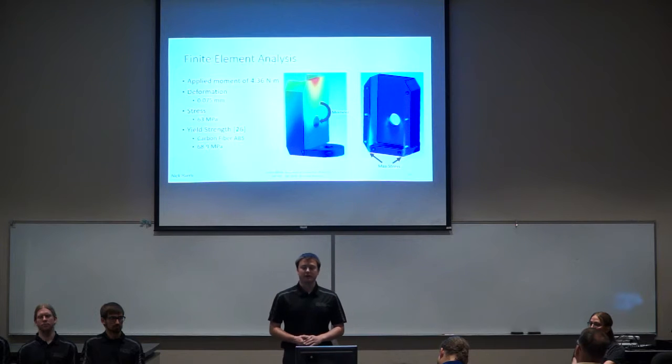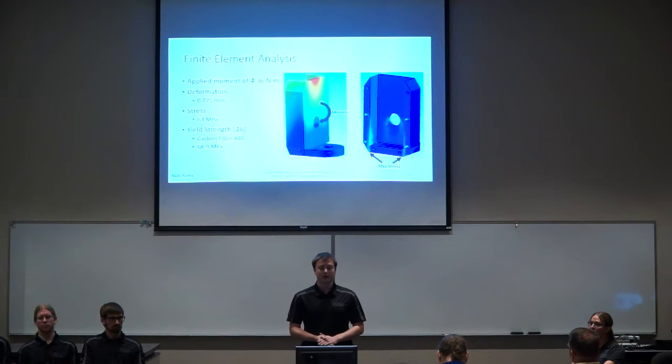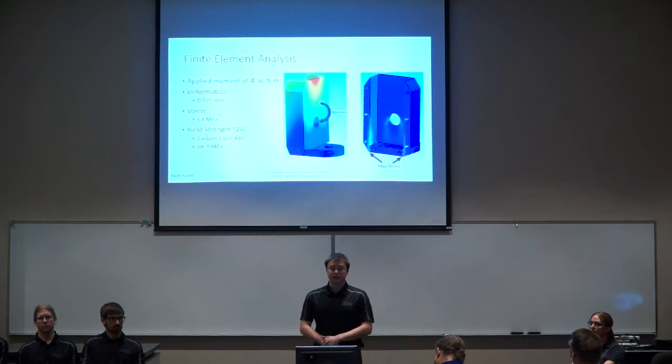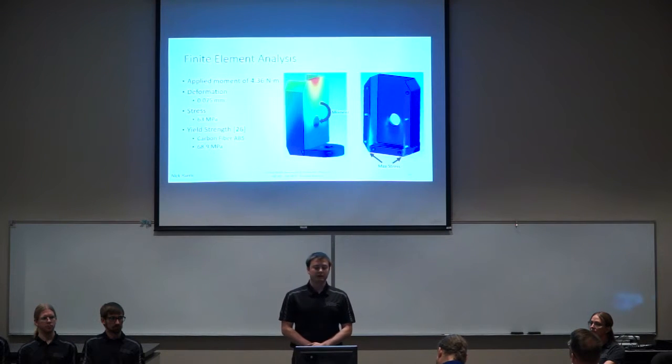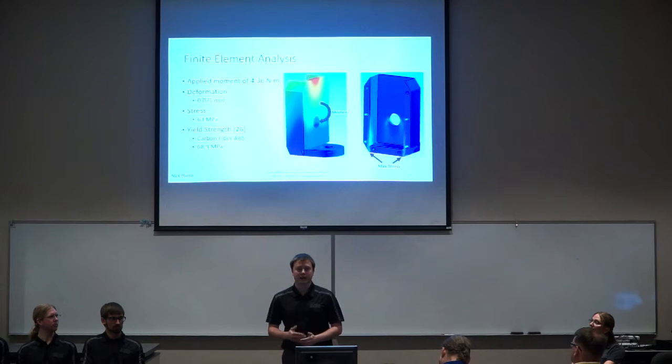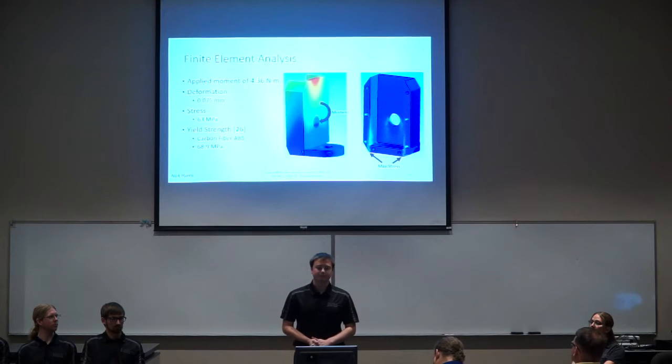And the overall stress at the max stress points in the right-hand picture was 63 megapascals. And the yield strength for the material that we will be using is 68.9 megapascals. This is all preliminary right now. We'll have to actually be testing these materials next semester to get the actual yield strength.